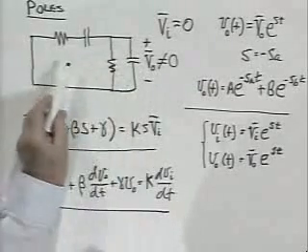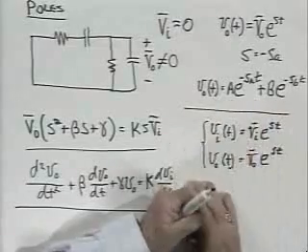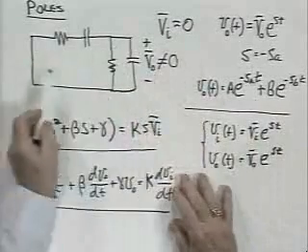are such that if the responses in the circuit are at that frequency, s sub a or s sub b, or more generally, exponentials, both of them simultaneously, then the network can have an output. There can be currents and voltages anywhere in this network without an excitation. And that condition, by definition, is what we mean by the unforced natural response of the circuit. If I dump some energy in the capacitors, stand back and let the circuit behave, what we get is the natural response, time response, transient response. And it occurs, in this case, with two exponentials of different frequencies, s sub a and s sub b, the sum of two exponentials giving us the voltage at this point, and the same would hold true for any voltage or any current.